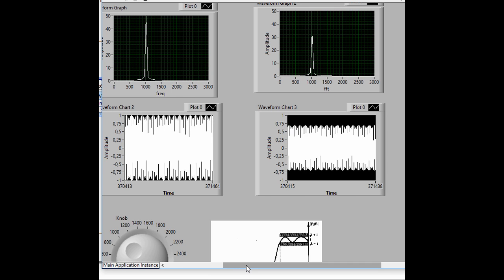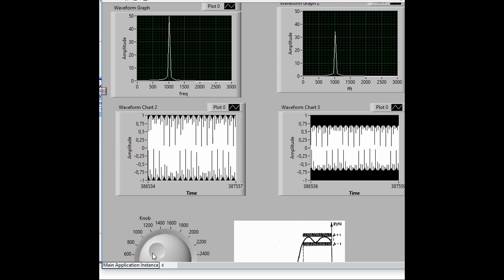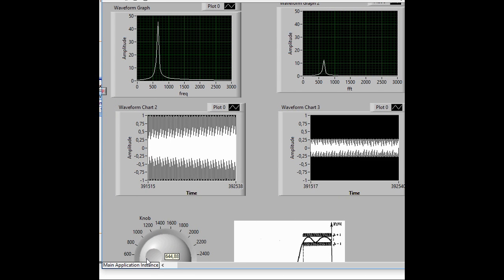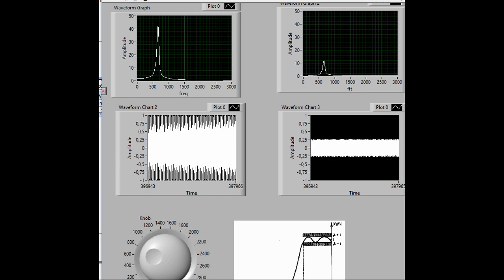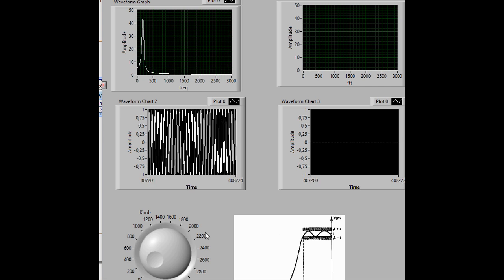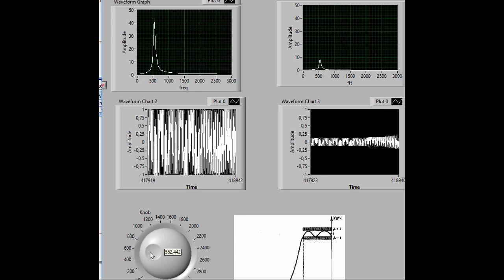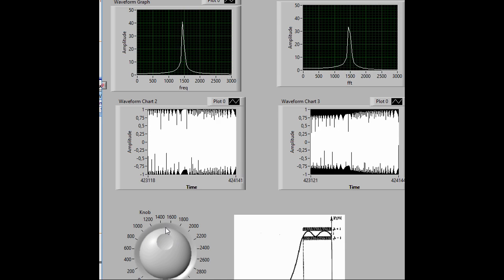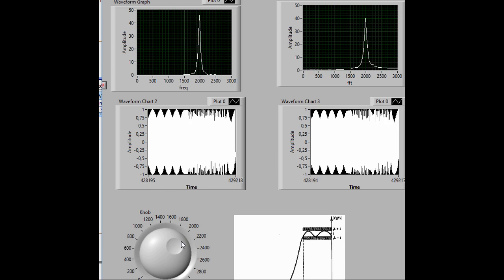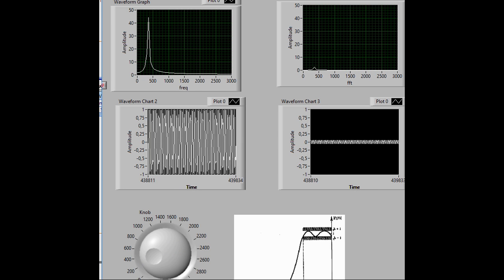This is before the filter, and then this one is after the filter. So we can see that the high frequency is going through. Remember, our cutoff was 100, so if I take this to 100, we can see the closer I get to 100, the smaller it gets. So that frequency is completely taken away there, and the moment I get to 100, we can see the frequency with the transition width is going through to the end, making it a high pass filter, because the high frequency is going through and low frequencies are stopped.